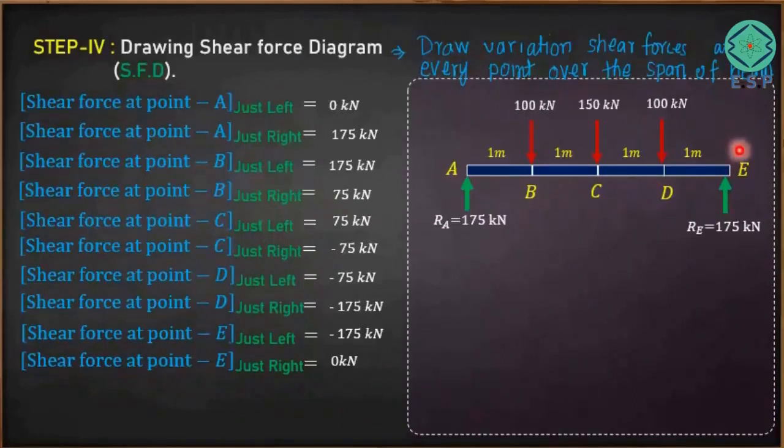So this is the free body diagram of the beam. We have already drawn that earlier. So what we do is we represent the beam and we represent all the forces acting on the beam. Now we want to get shear forces acting on the beam along its length at each and every point. So I have just marked all the points by the vertical lines. Okay. This horizontal line will be having shear forces on it.